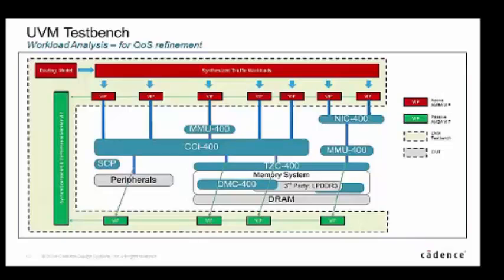One last question for me, what's the simulation performance of this? So there's a question on simulation performance. From a subsystem point of view, you're talking about hours or less than hours. We have some customers who run this on the full SoC, full application, mobile application processor. Obviously taking control of the masters, so for instance the processors aren't active, but that's still doable in simulation, 7 or 8 hours. You don't want to run lots of them.